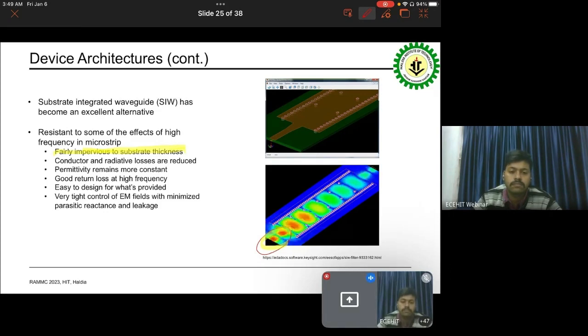These are basically, if you think about it, because of that sandwiching property of those two vias and that top and bottom plane, a waveguide, it's a field sandwich. Because of that, there's a lot better field control. You don't end up with as much radiative loss coming out of it. You don't end up with a substantial amount of leakage, with the exception, again, down here.